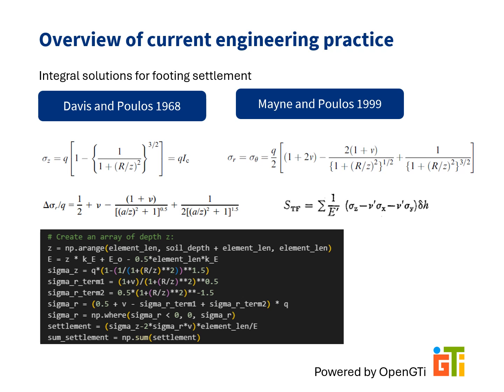While it remains a good practice to perform numerical iteration to evaluate settlements precisely using the elastic displacement theory upon which this design chart is based, this regression method does not aim to replace the original integration method. Instead, it offers an alternative to both the integration method and the traditional graph reading method, establishing a closed form equation that simplifies computation while preserving accuracy.